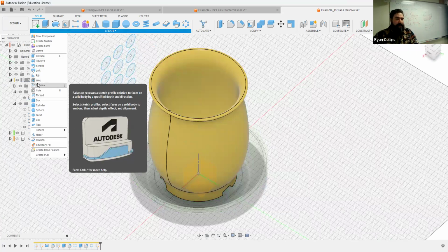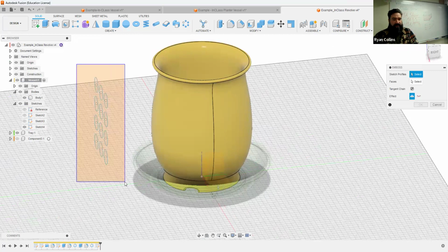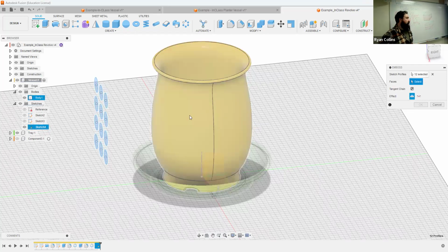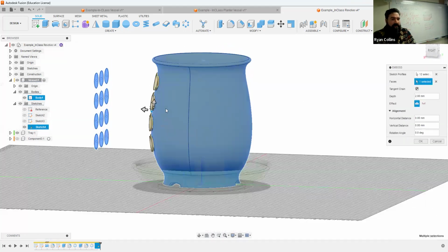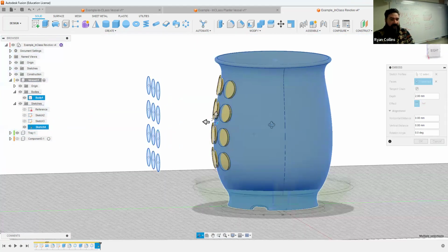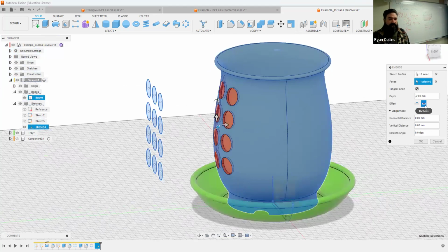Further down, sort of kind of the same thing, but different. So again, select all the things. And now, instead of pulling and pushing to get where I want, I can just select the face I want it to go to. So now it makes a curved extrusion, essentially, which is called an emboss. If you want it to cut inward, select deboss. Automatically cuts inward.